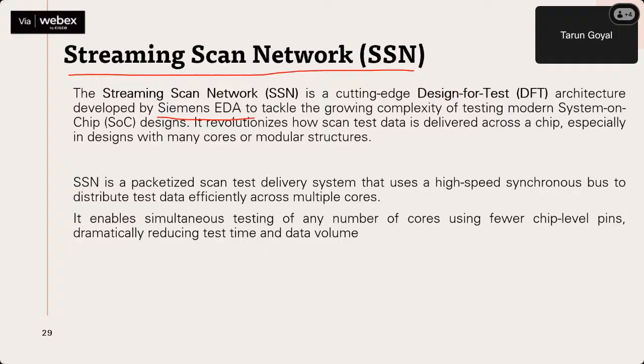So basically, at a high level, what it's doing is: now size is increasing, and more and more patterns are required to test multiple cores. So how do we reduce that test size without any other penalty? I'm taking one very simple example. Suppose we have designed those flip flops that we were talking about, right? We were having a clock and keeping the SI data when scan enable was high, correct? And this clock was some frequency. Suppose this frequency was 50 megahertz.